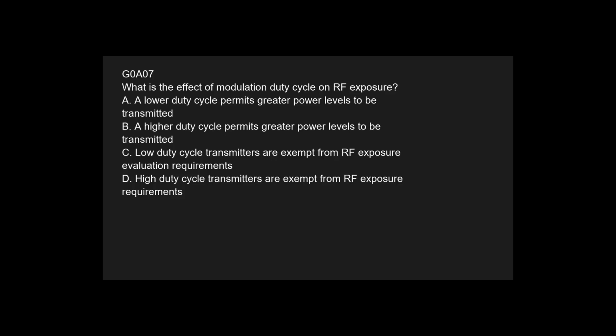Question: what is the effect of modulation duty cycle on RF exposure? The correct answer is A. A lower duty cycle permits greater power levels to be transmitted.